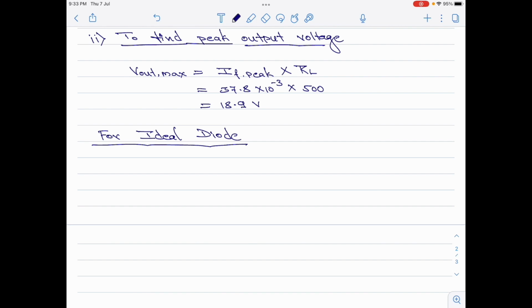You should note that when the diode is ideal, the voltage across the diode that is required to turn on the diode is 0 volts. So, the value of the knee voltage will become 0 volts. Also, it does not offer any resistance to the flow of current across the same and therefore, the forward resistance will also become 0. Let us now write that down here.